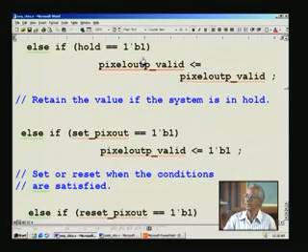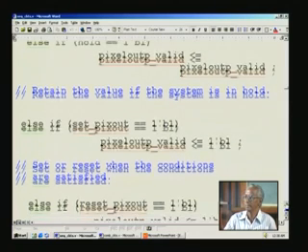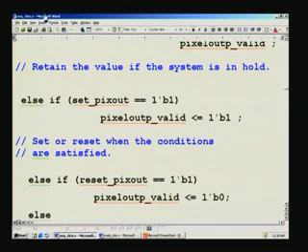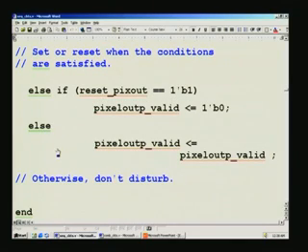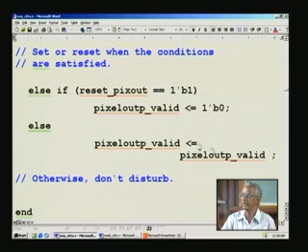That is how it preserves at the time of hold, and when hold is removed, it continues from where it left, it does not start from square one again. That is the beauty of using a hold. And this also we have seen, if statements and else if statements to realize when such and such condition is met, do this, otherwise do that. So the final otherwise is with an else, that will mark the end of this entire always block with if else if notation. And here you see that once again it is saving back the same thing, because we do not want to lose its contents.